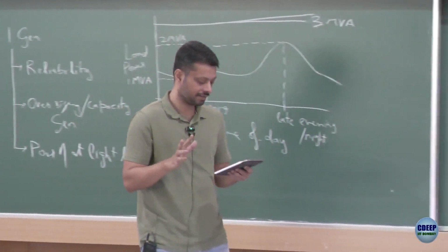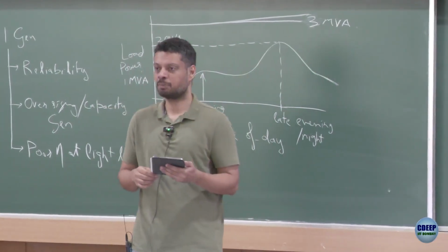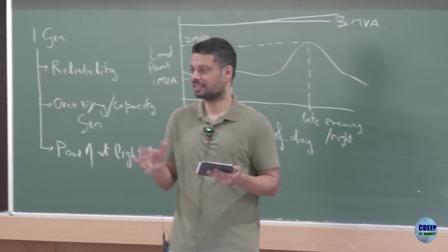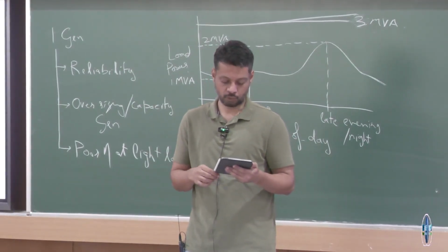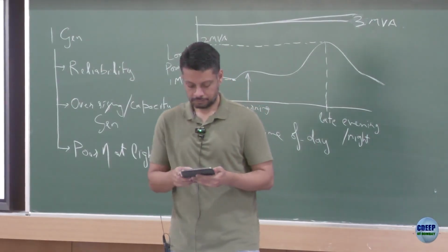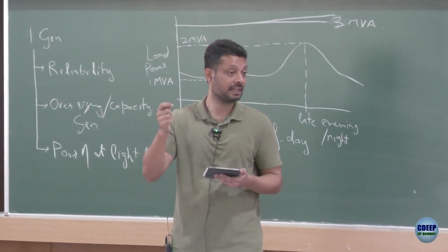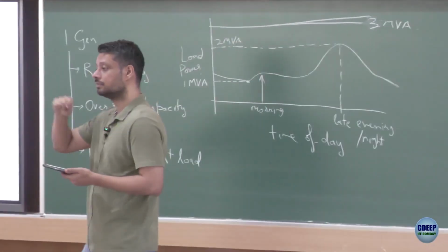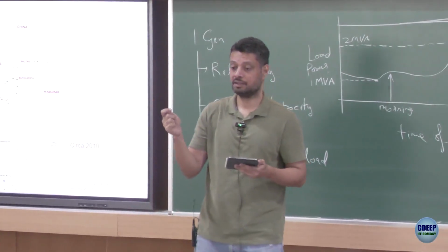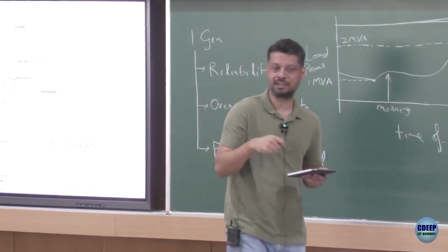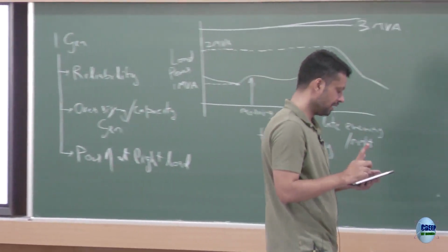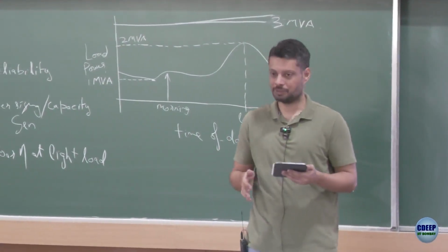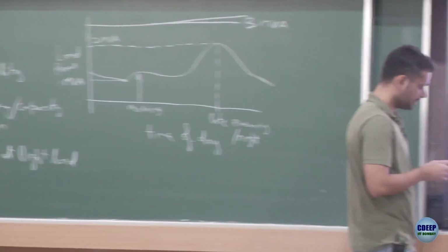With Nepal, I think the data appears to be more accurate. It's about a 1.2 gigawatt link, with Bangladesh a 1.16 gigawatt link, and with Bhutan about a 2 gigawatt link. With Bhutan, we have a synchronous connection, that means an AC line connecting the two power grids. With other countries, we again have HVDC connections which are not synchronous. I have to check the value for Myanmar because 3 megawatt does appear to be really low. So I need to check that.